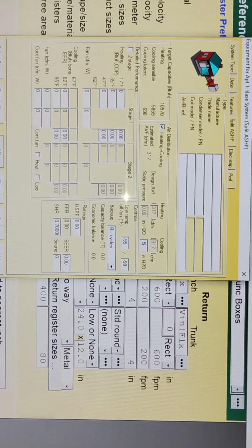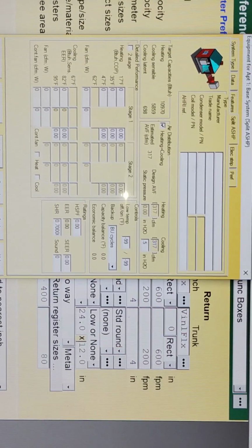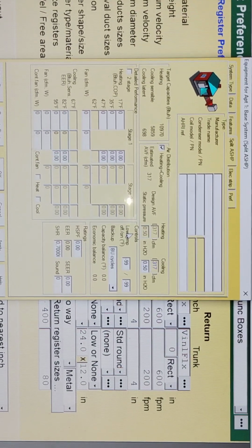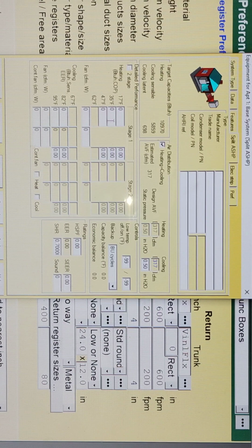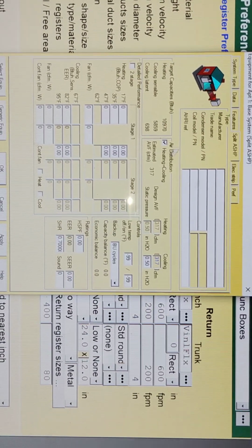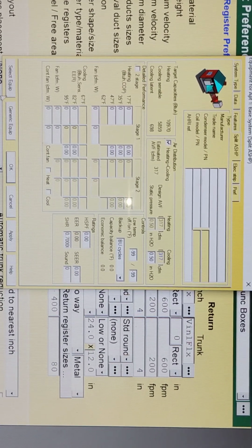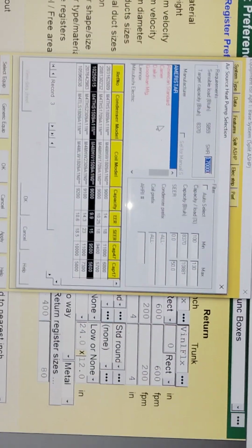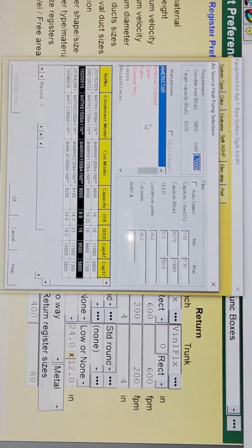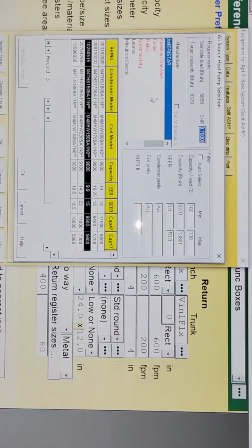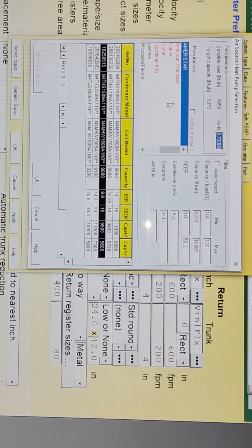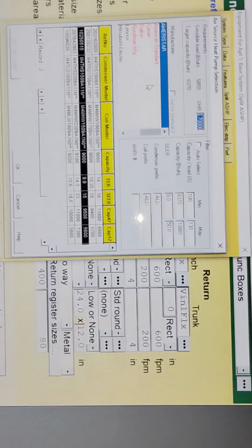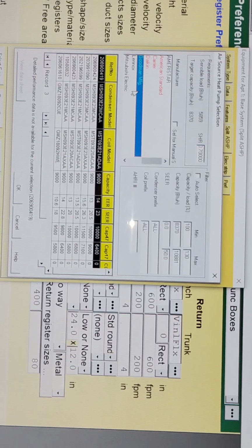Most manufacturers have a design static pressure of 0.5 or thereabouts, so that's what we're going to use here. We're going to let all of this fill in depending on our equipment, so we're going to go down and select equipment. Just so you know, because this is 0.7 tons, we're probably not going to find something that works with Manual S until we add in our other heat loads, but we'll give it a try.